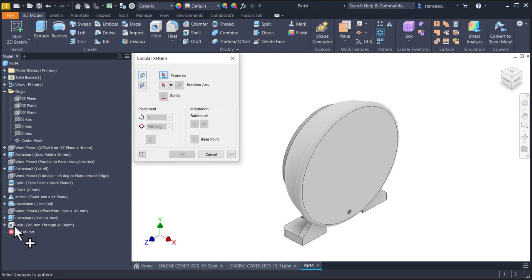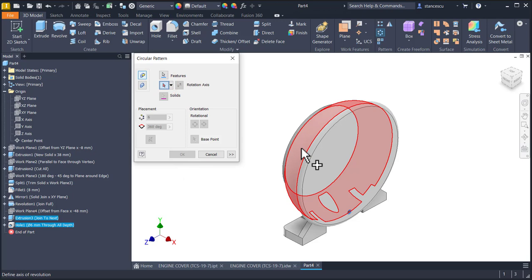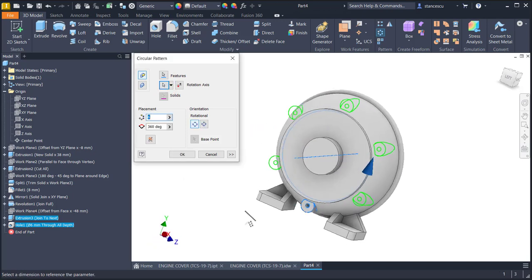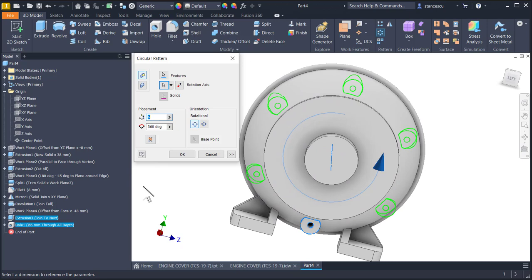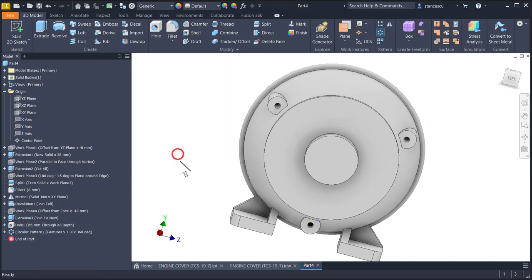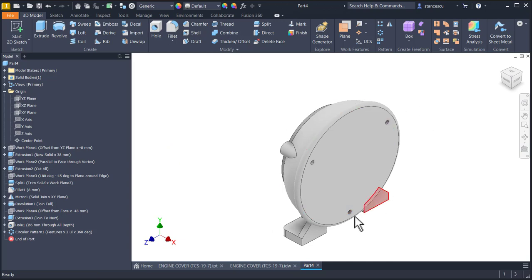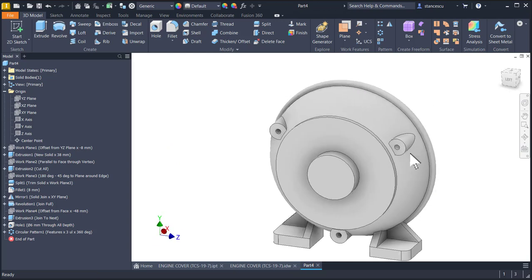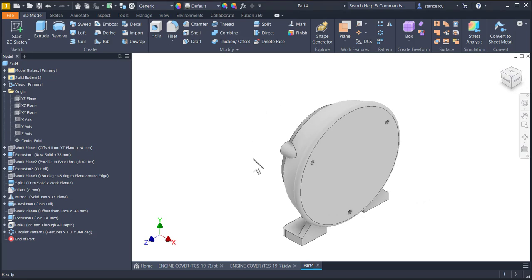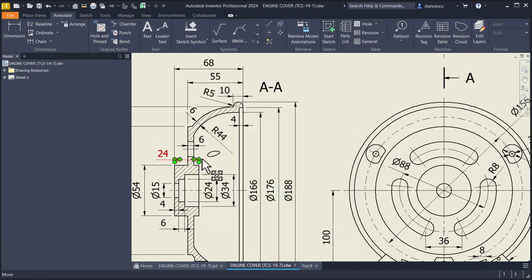Okay, now we apply circular pattern for the last 2 features about this center, not 6 but 3. Okay, you see here 3 holes and here 3 bosses. Only now we create the internal hollow revolving volume. Dimensions are almost placed in the previous sketch. We'll use it.